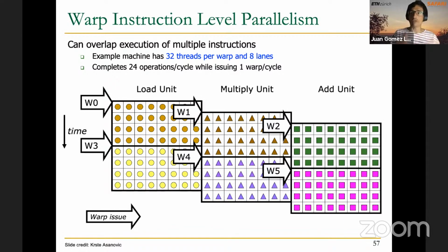And recall the idea of vector processors and array processors at the same time. Here we have different instructions at the same time as in a vector processor, but also as in an array processor, we may have different instructions in the same unit as well. And actually that's typically what we will have for additions and multiplications, that in reality they are executed on the same SIMD lanes, and the INT32 or FP32 or FP64 units that you have previously seen in the GPU core of Nvidia A100.